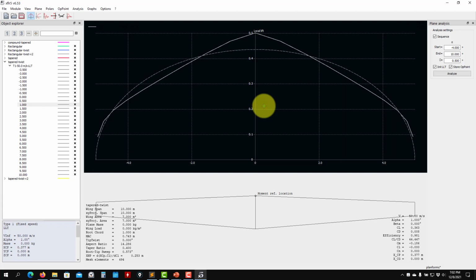Things get even worse. So we're just focused that we want towards the tip. So probably 20% of the span, if you manage to get it elliptical, is enough. Our semi-span here is 5, so as you get 1 meter close, I think it will be a very good result. You are reducing the intensity. But see that this is the idea. Here, see that it's very good results, very close to the elliptical. So this can be controlled by